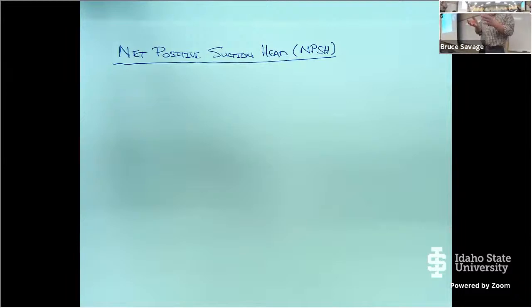And then they'd cavitate the pump, and then they'd pull that out, and the graduate student that was working on that got to go in and count all the little pinpricks on that piece of aluminum. They put a little grid on it, and they'd count all of them up. Pretty tedious work, but it gave some idea of how fast the cavitation was damaging the material. Okay? And what you had to do to stay away from that.